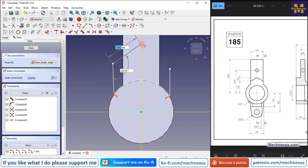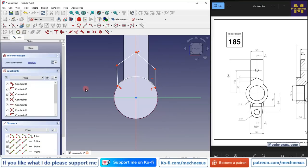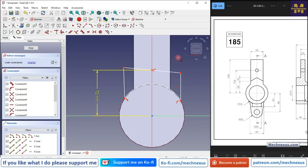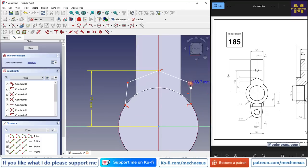and add a coincidence here. Now here if you see, this 16 mm is given, and if we add the distance we will get the height of this point from the center. So I will select these 2 points and add a smart dimension which is 56 plus 16, and now I will move this point down.